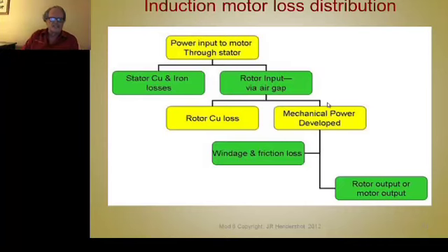And then also in the stator you have losses in the iron itself, in the steel, in the laminations, in the sintered material, which is made up of magnetic material. And since these machines are bipolar, in other words, the flux is north and then it changes to south, that means there are flux reversals. That means it goes through zero, and that flux is a dφ/dt, and it's based on the commutation frequency and the PWM frequency that you use to chop the voltage to control the current, so that you get both eddy current losses and hysteresis losses in the iron.